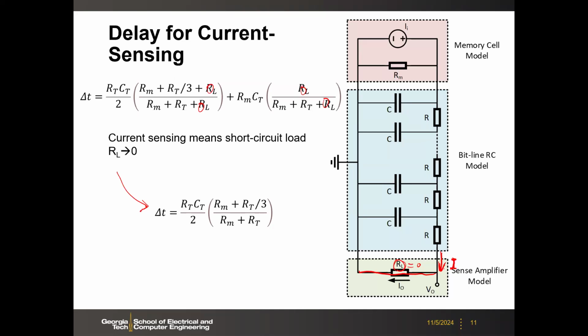For voltage mode it goes to infinity. For current mode it goes to 0. I mean, in the ideal case, of course. With real transistors the impedance goes large or small, but it won't be perfect infinity or 0, because you still have some transistors in that path anyway.